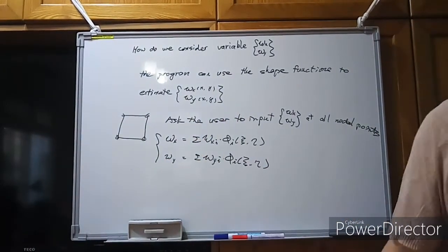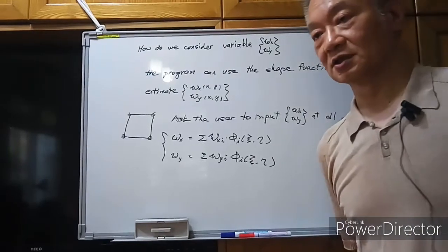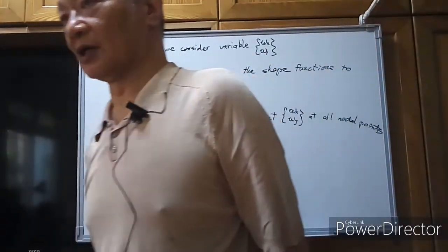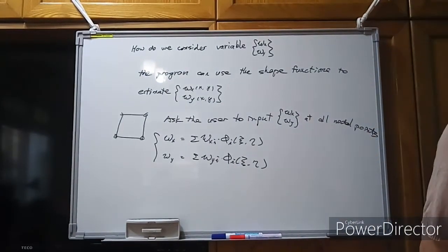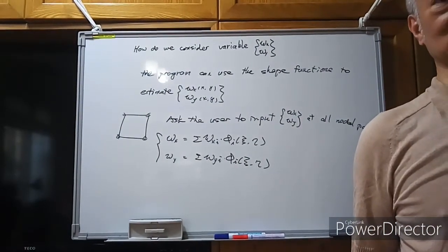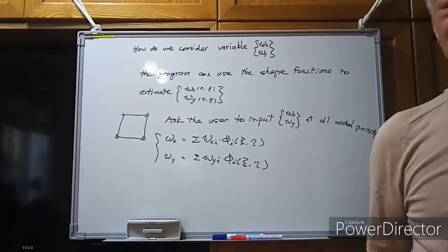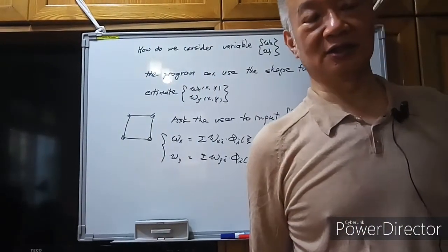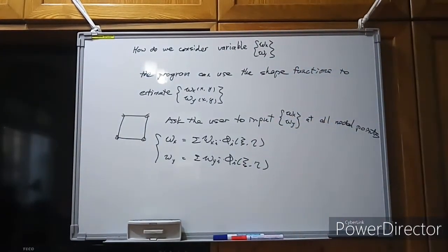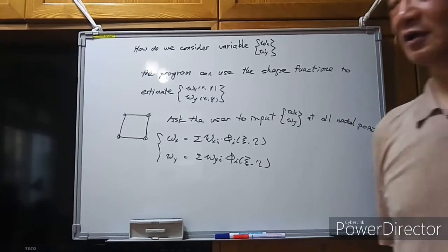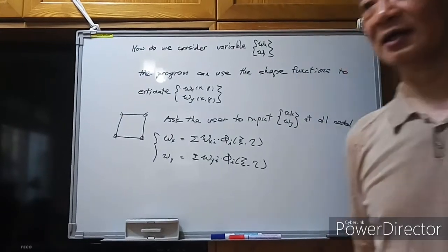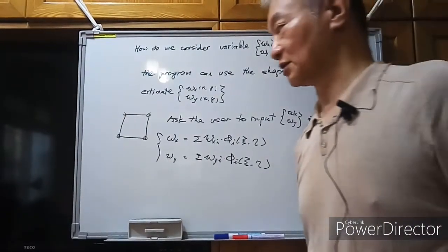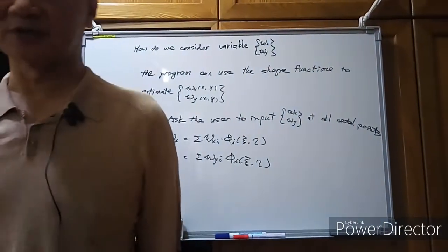in the entire element. Remember, the interpolation functions can be used to interpolate continuous functions inside a domain, and they can be used for any physical values. No matter whether the physical values are the nodal coordinates x and y, or the nodal displacements ui and vi, with the interpolated functions being the displacement functions u and v.